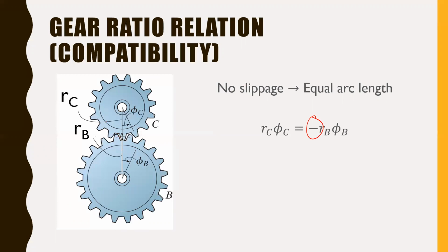If we were to rotate gear B by some angle that is clockwise, that means that if we started with this point being vertical and we've rotated it, we've rotated that amount of arc length, right? That's the length along the perimeter of this gear that we've rotated. That's given by this function here. Negative just indicating that it's in the opposite direction of the other gear.